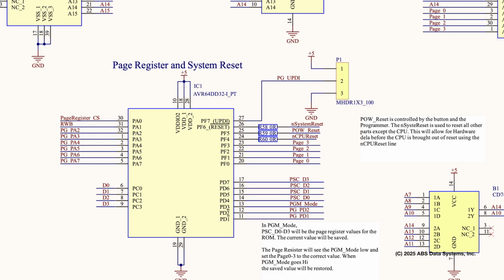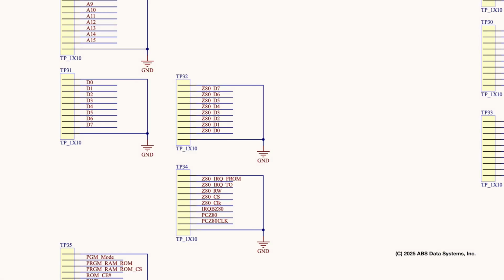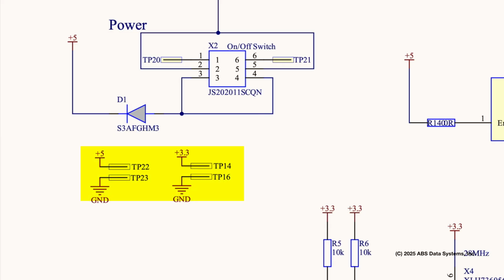As a side note, as I'm looking at this circuit, I'm reminded of a couple of things that I've learned along the way that I'd like to share with you. The first is the use of 0 ohm resistors as placeholders. If I lay down a 0 ohm resistor and I find out later on that this was an error, I can remove the resistor and now I have 2 pads to solder wires to. The second is adding pads or test points everywhere, especially for ground. You always want a ground pad closest to where you're taking measurements from.